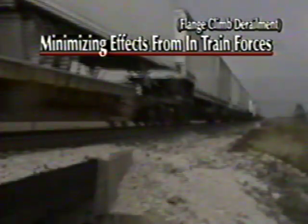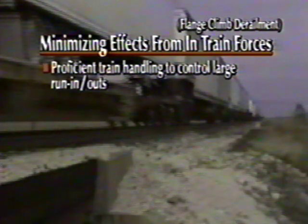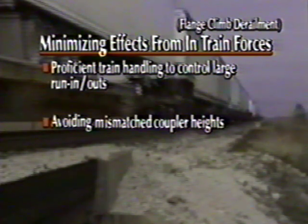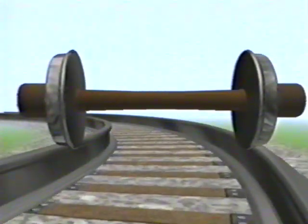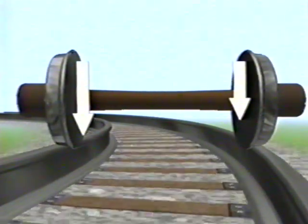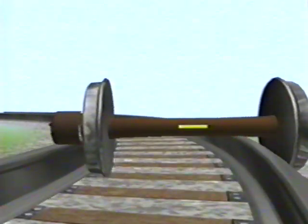Let's review the factors that minimize undesirable reactions from in-train force, like effective train handling that controls large run-ins or run-outs, ensuring that coupler heights are within regulatory limits, and following your railroad's train makeup rules regarding long car, short car combinations. The next event in the flange climb derailment scenario was the transfer of load from the outer wheel to the inner wheel to the point where the outer wheel climbed over the rail. What factors contribute to this load transfer?